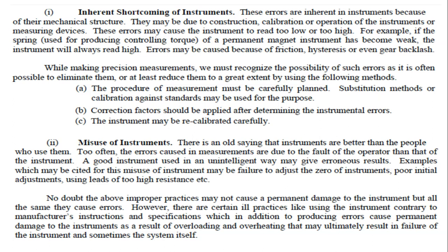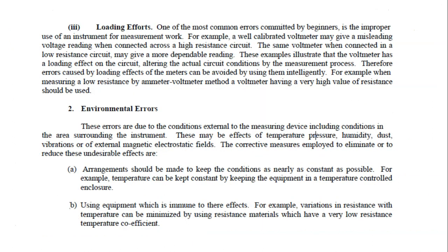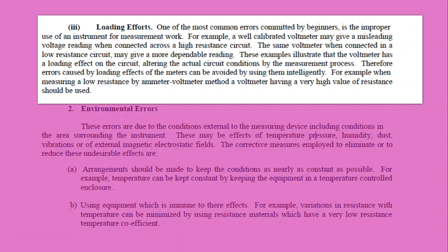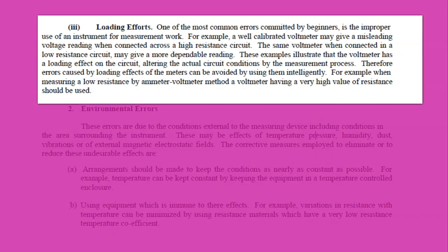The other reasons can be using leads of too high resistance. The third one is loading effects. If we are loading the instrument more than the maximum limits that have been specified, it will lead to error in the measurement.